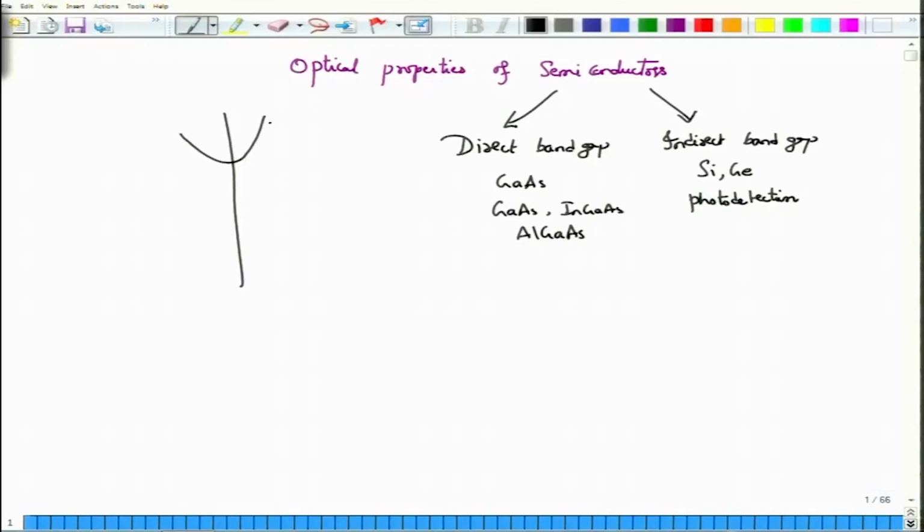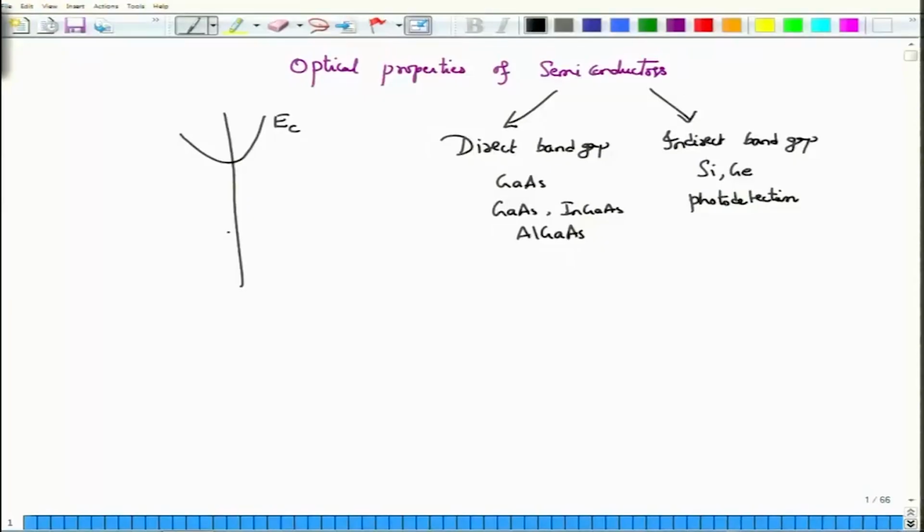So you have the conduction band not actually flat as we have shown, but that flatness is actually along the length of the crystal. What we are going to plot in this one is the horizontal axis, which corresponds to the momentum vector k along a specific direction. So, for example, for gallium arsenide, this might be the crystal axis direction, as we would call it. Along this crystal direction, as the momentum keeps going, this is how the energy versus k diagram would look. For a direct band gap material, this is roughly how the energy band gap would look.